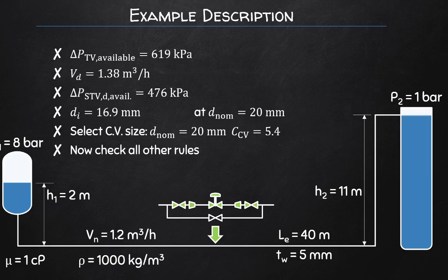So if you're sitting at your desk one day in industry and you need to install a control valve, you would likely get a manual or a list of specifications from the supplier before you go out and buy or order a control valve. You would first do these calculations and make very certain that you buy the right one. And in general you would end up buying more than one, because remember, you might have to do maintenance on a control valve and you need a second backup or even a third backup.